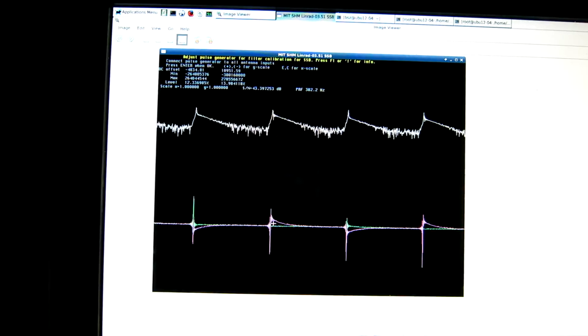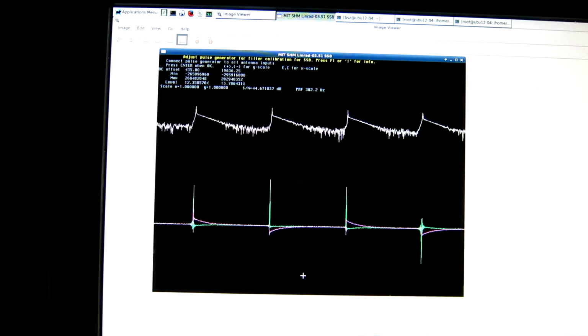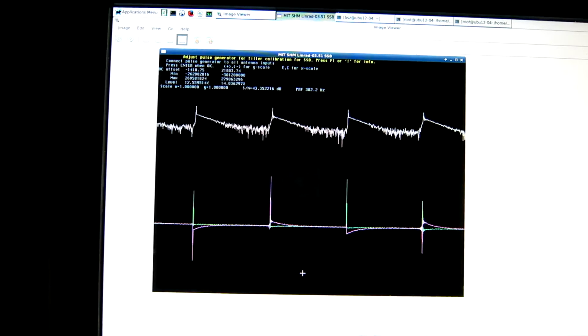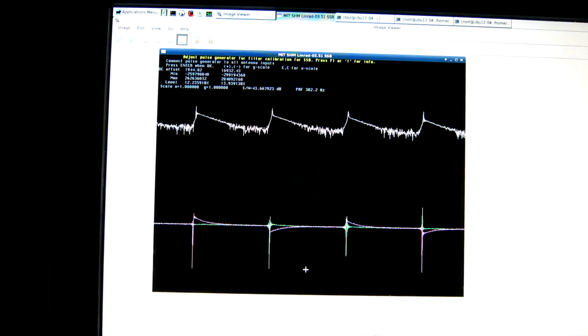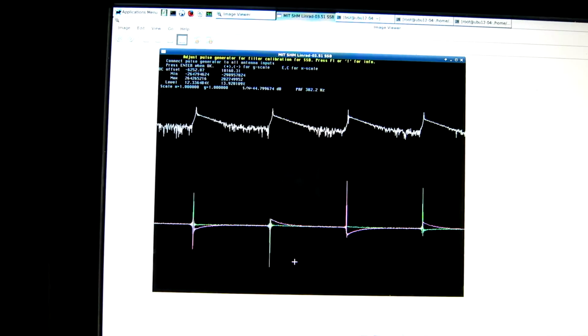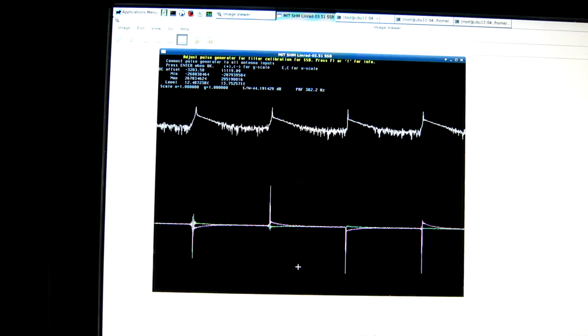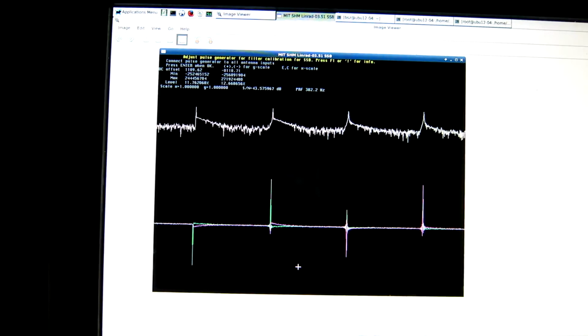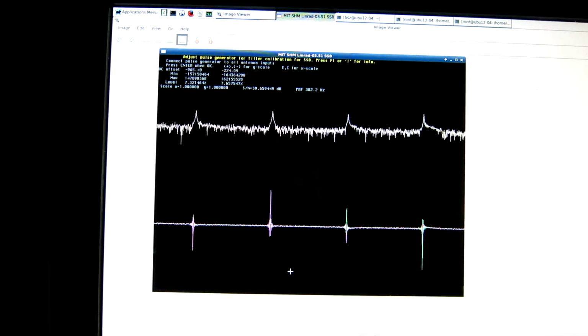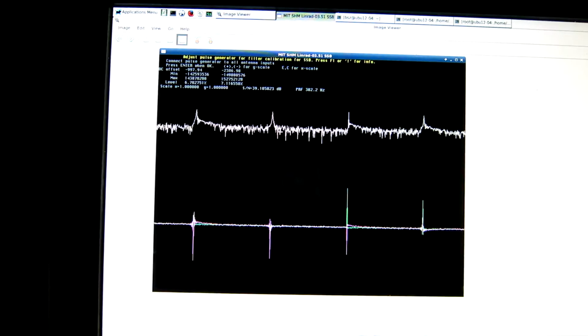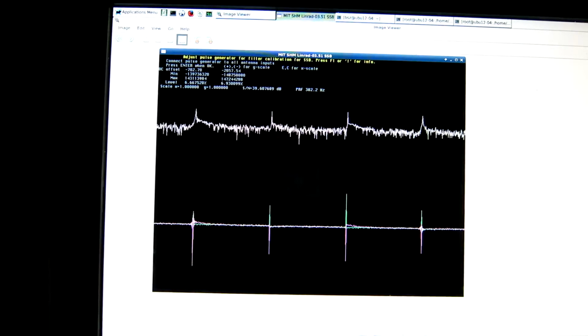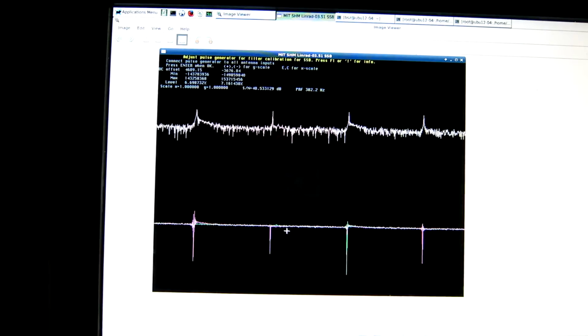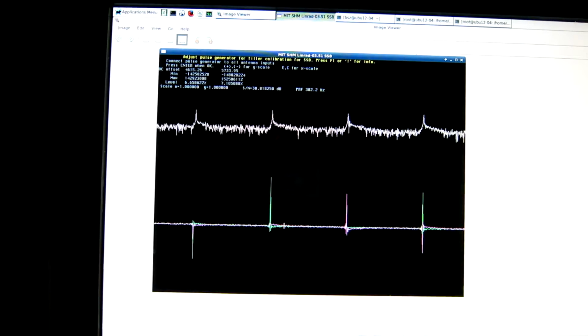And we can see here it's a DC voltage that extends for a long time after the pulse. That's an artifact from having saturated the mixer, or maybe the input, the amplifier after the mixer. I don't know exactly, but this is too much signal. So I go back to here. The white curve is the power logarithmic scale, and here magenta and green is I and Q.